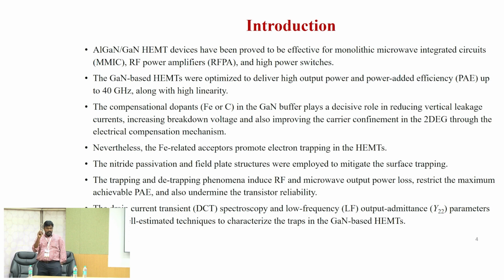The model estimates the two-dimensional electron gas reduction during power switching, like RF switching operation. Whenever you do characterization, you do not get the exact trap activation energy.